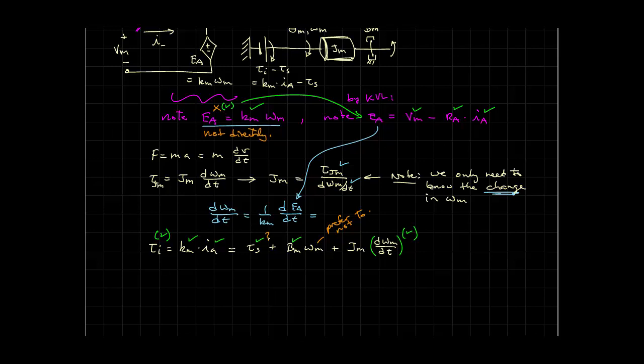Clearly, if you spin down the motor, you have to have current flowing here, right? We have assumed there's going to be some kind of torque that is going to be applied to the system, to the rotational inertia, to slow it down. And it's a torque that you need to be able to observe. So if you do spin it down, there are test conditions that you can set up where you can readily determine or measure, observe the actual torque that is being applied to the rotational inertia portion of the system, at least to be able to get a very good estimate of that.